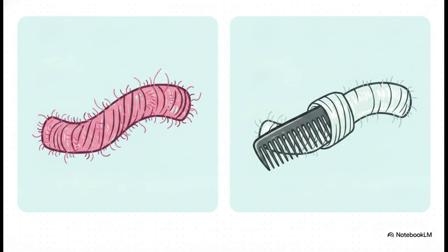Now, zooming in on those short staple yarns, we've got two primary processing methods, carded and combed. During spinning, carded yarns don't actually have all their short, messy fibers removed, which leaves them a bit less compact. But combed yarns use an extra machine, literally a combing machine, to pull those short fibers right out. So your memory hook here? Just remember that combed means cleaner and compact. Taking that extra step yields superior strength, a much smoother texture, and a really nice lustrous finish.